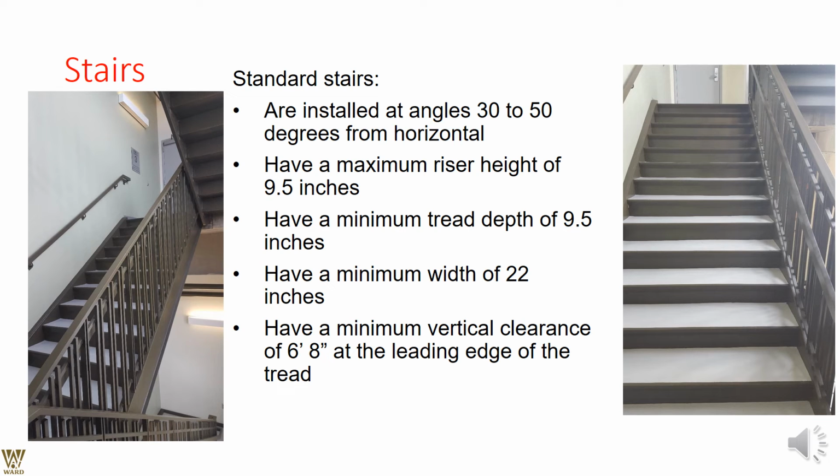Talking of the standard stairs, basically they should be at an angle of 30 to 50 degrees, not beyond it. Beyond it becomes a little bit more tough. Have a maximum riser of 9.5 inches, a depth of 9.5 inches. So it is absolutely square in shape, but only the length varies. Remember, only the length varies.